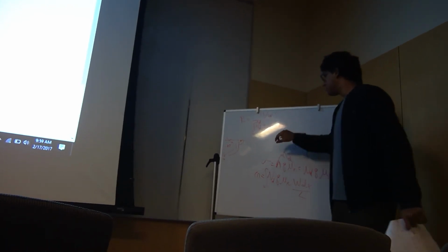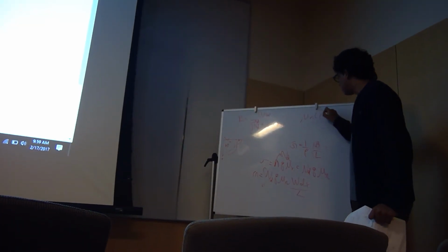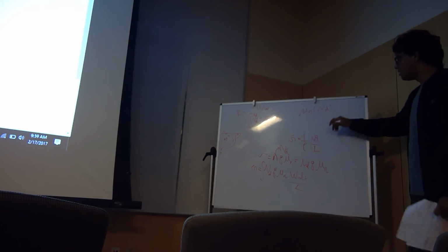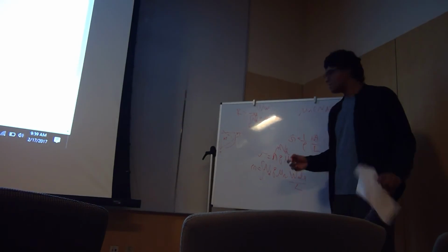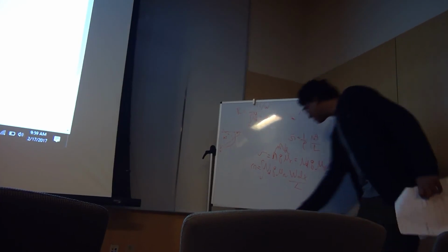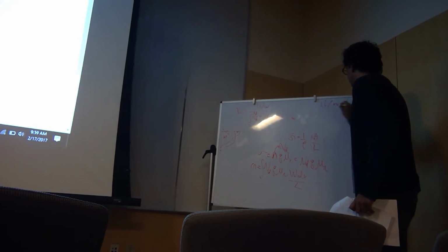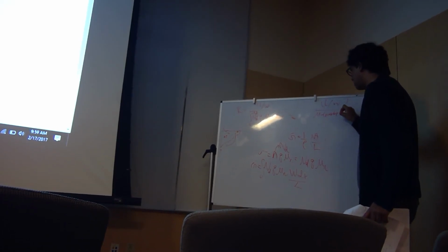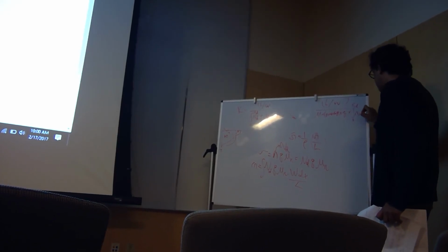Now you need to make some assumptions here. Your mobility is in general going to depend on your doping, but assume that your doping is so uniform that this integral just becomes a product. You get what I'm saying, right? It's engineering mathematics. Just take out this mobility. Just take the mobility at the peak doping, times charge times the integral from 0 to xd of Nd dx.